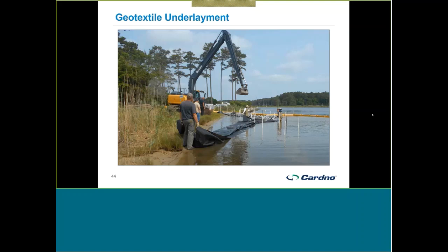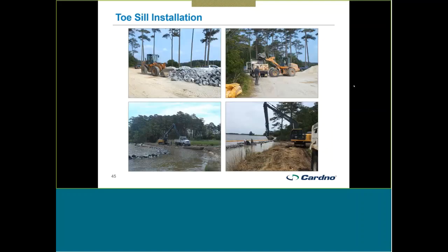First step is to put out some geotextile so that it provides a foundation for the rock so that rock doesn't settle down. Our bottom here was fairly firm, you can see people aren't sinking down. It's fairly firm sand with a thin layer of mud over top of it. But it's still a good idea to either have bedding stone or some geotextile to make sure that rock doesn't sink down into the black ooze.